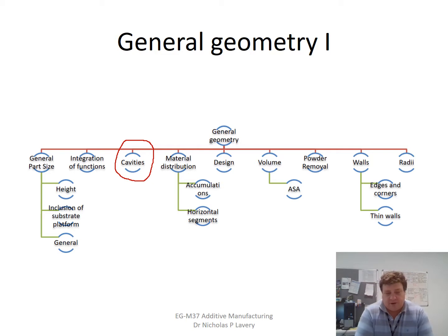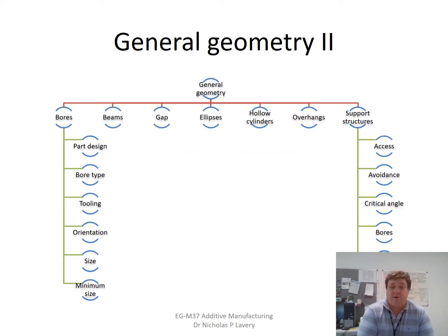In terms of a design plan, we want to be able to incorporate the build in such a way that sharp corners, if you can avoid them, much the same way as you would do with a powder metallurgical process like powder compaction, sometimes if it's not part of the design, then rounding off corners is sometimes better for a build in transitions in the vertical direction.